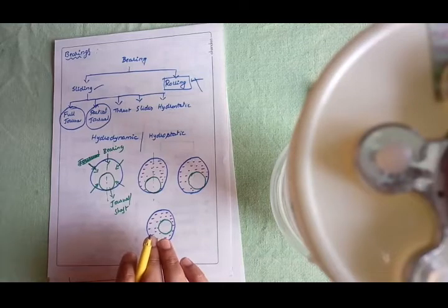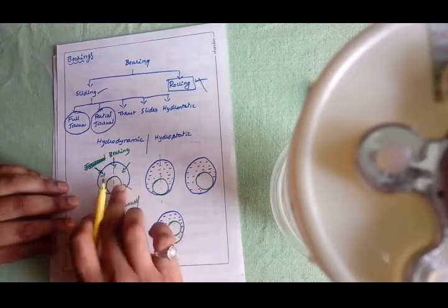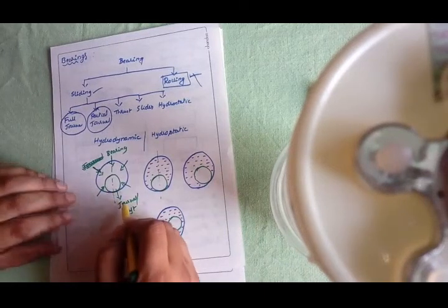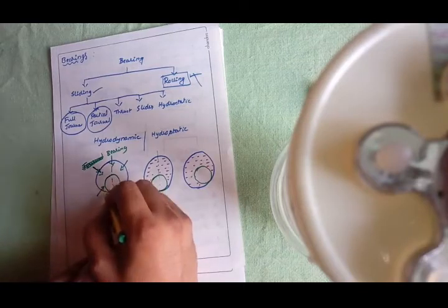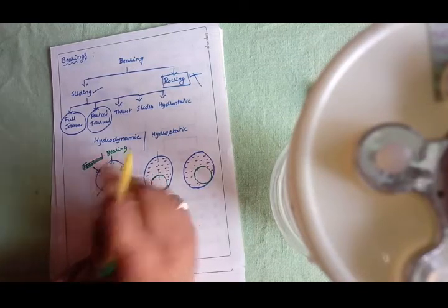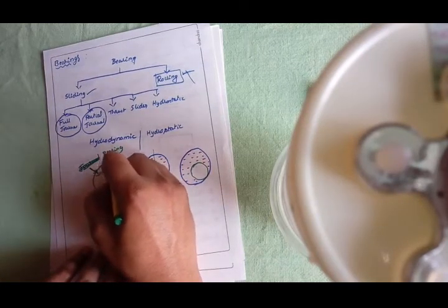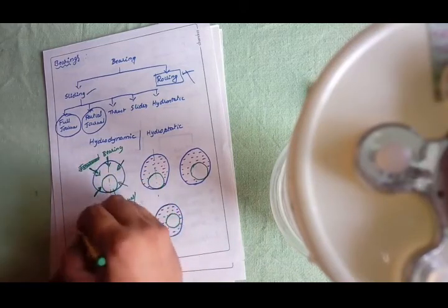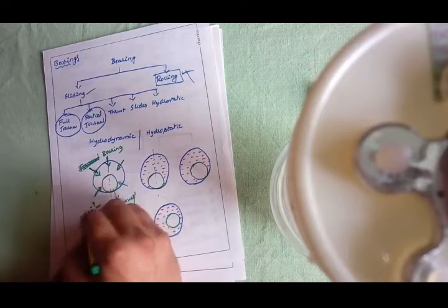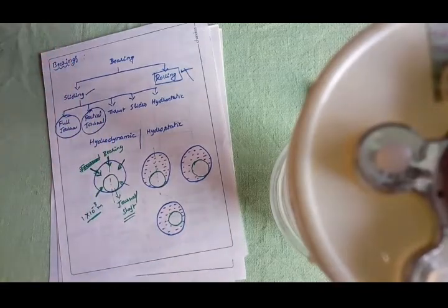First, what you need to understand here is, I have written a circle in green color. It's a journal or a shaft. The circle in blue color is a bearing surface, and there are oil holes which allow the oil to enter into the gap which has been provided here. Generally the gap between the shaft and the bearing will be very small, of the order of 10 to the power minus 3 meters, but in order to understand the concept, I have exaggerated the diagram.